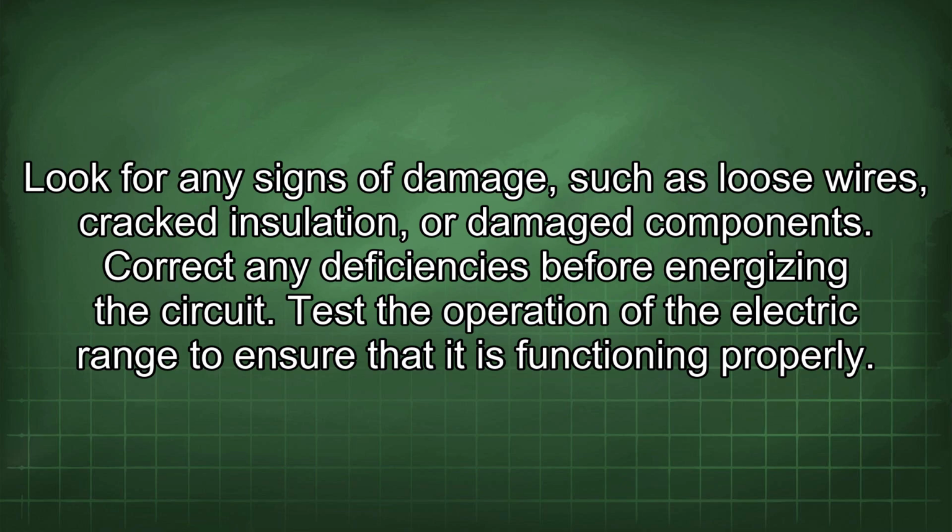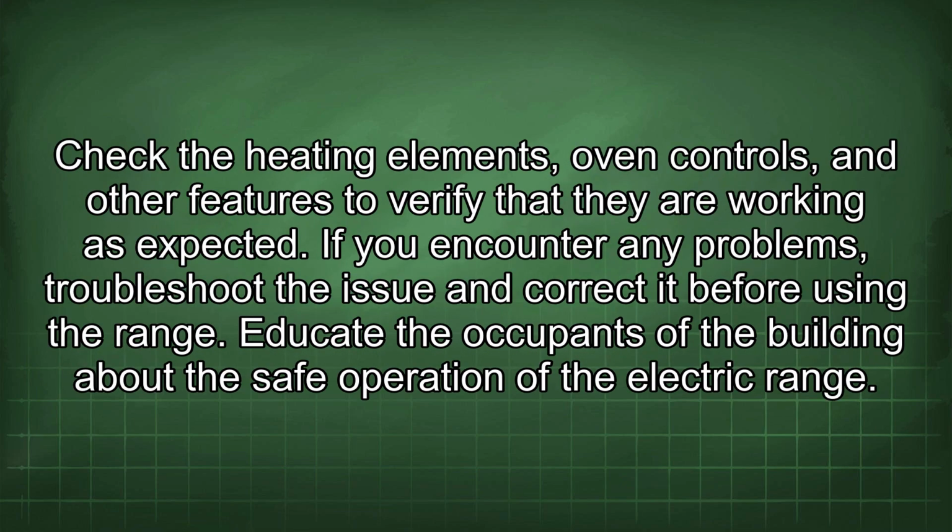Test the operation of the electric range to ensure that it is functioning properly. Check the heating elements, oven controls, and other features to verify that they are working as expected. If you encounter any problems, troubleshoot the issue and correct it before using the range.